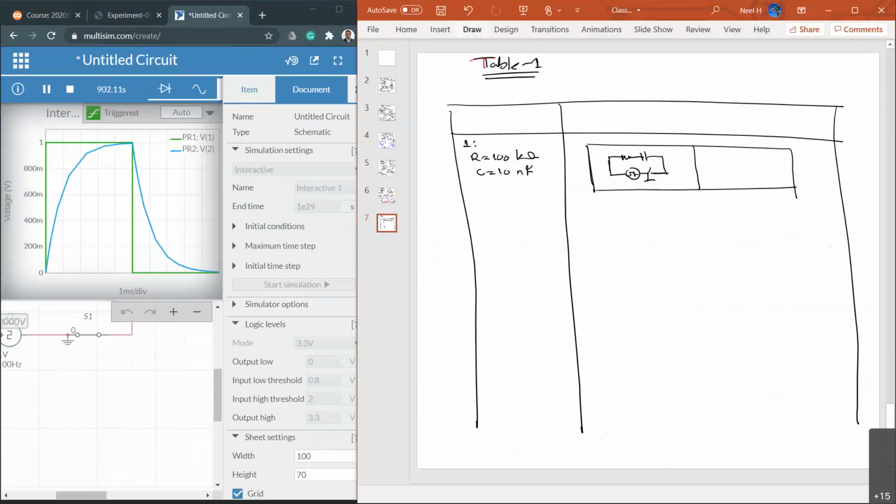And this point should be grounded properly. Capacitor value, resistor value, voltage value, all this stuff should be visible. And then your graph here, right? The graph should show the charging curve and the discharging curve at least. So inside here, you will see the charging graph, capacitor voltage, discharging graph. All of those should be visible.